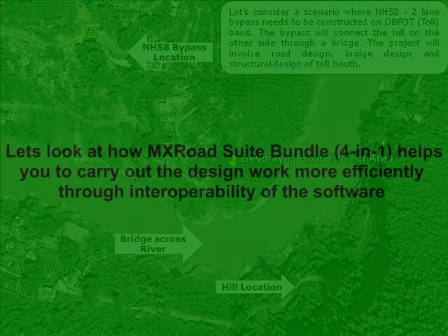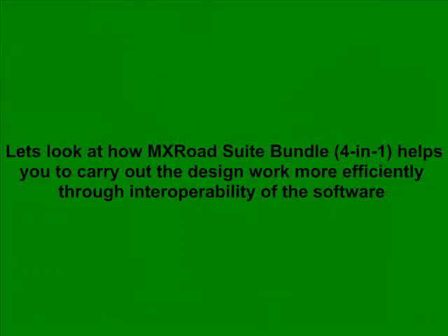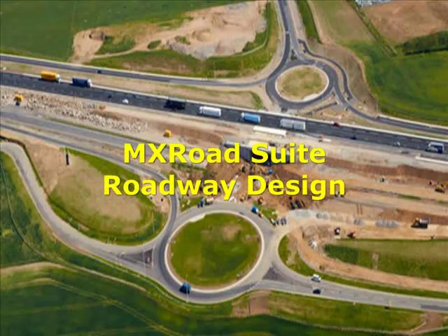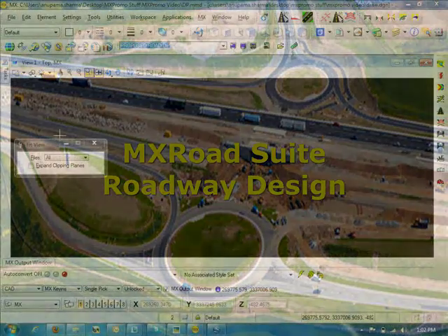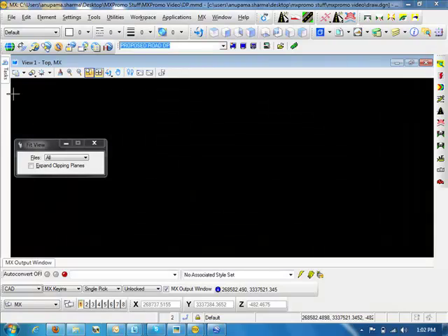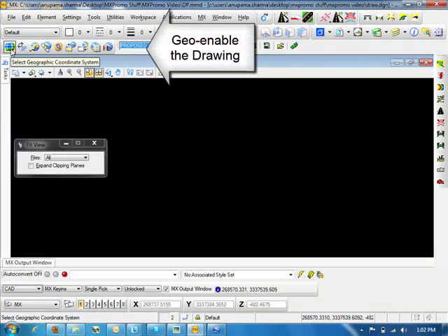Let's look at how MXRoad Suite Bundle 4-in-1 helps you to carry out the design work more efficiently through interoperability of the software. Let's first look at the workflow for MXRoad. Data can be imported in a variety of formats such as total station, dumpy level, CAD drawings, but for this example we are going to use the Google Earth data and use it as a terrain model.